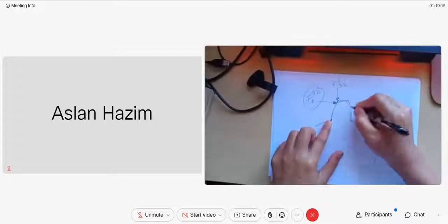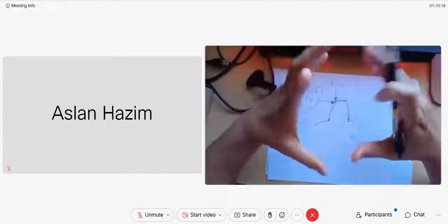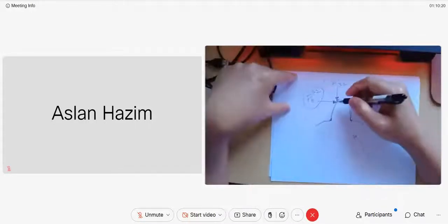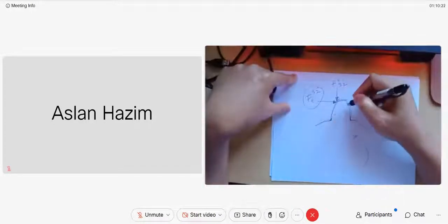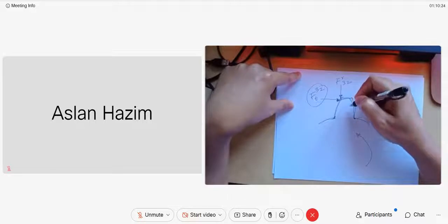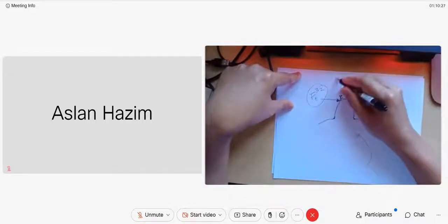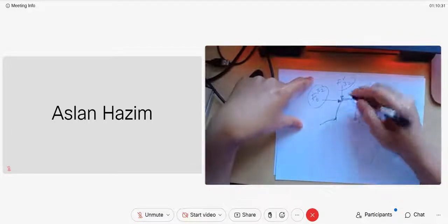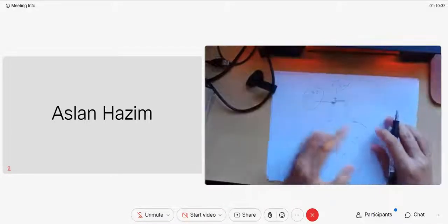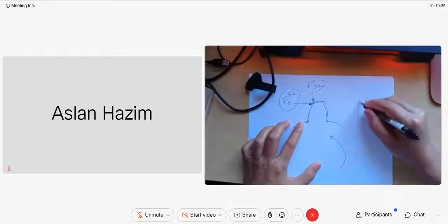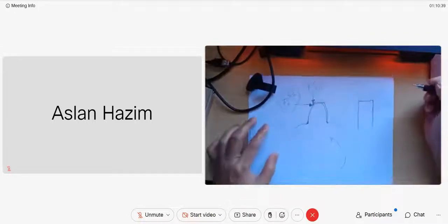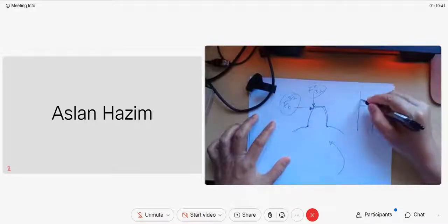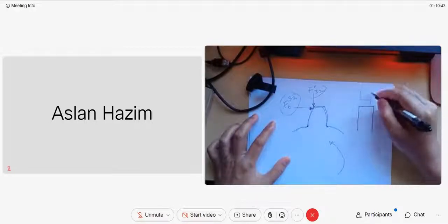It will affect the strength of your gear tooth. So will this gear tooth survive or not with this F tangent? This one we can ignore. Actually, there will be some axial force on the gear tooth, because let's say you assume the gear tooth is one cantilever beam, like this. And the cross section is a rectangle, right?